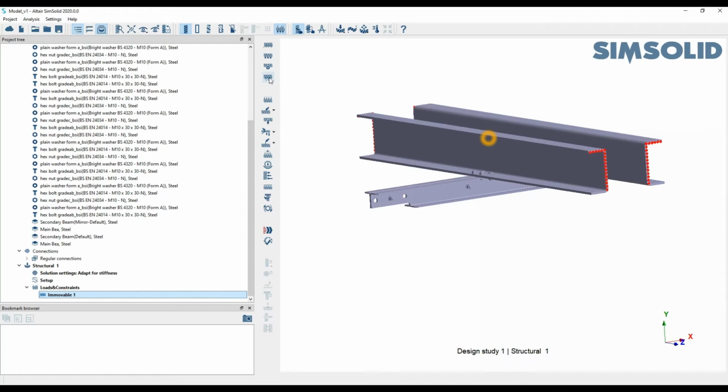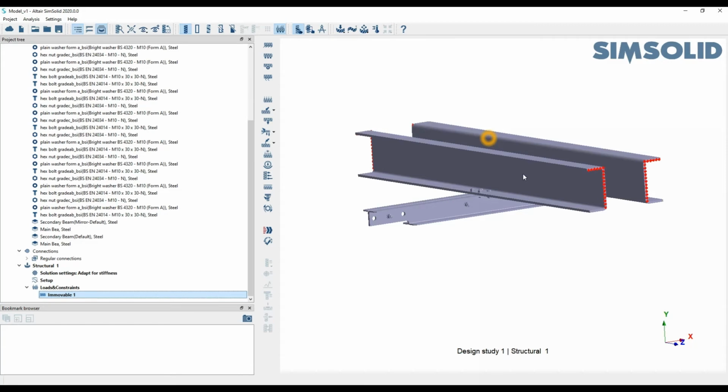Now on this next part, you'll see that we also have a spring support. So this is like establishing an elastic foundation for, say, if something isn't actually properly constrained, but there is a bit of leeway to how much it can move. You can give that sort of elastic foundation in terms of stiffness values in X, Y, and Z.